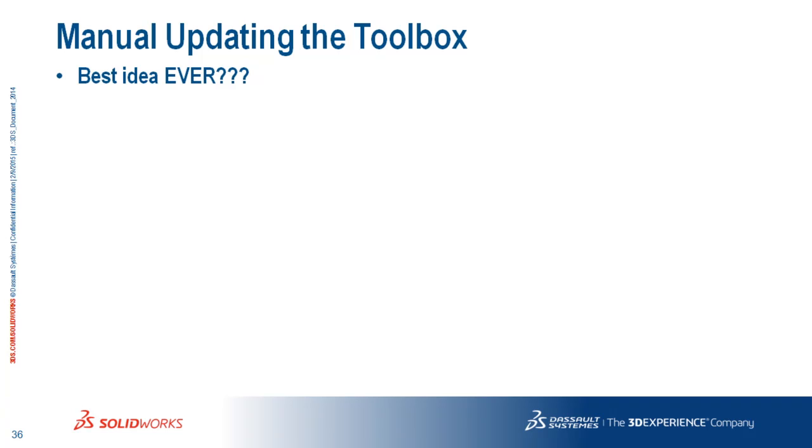Go back in, check it out, yep. All right, so one trick on the admin image to get that to flow through is to just change the setting to write a toolbox to the C folder, C, SOLIDWORKS data, and just dump one on the individual user, okay? What happens then is it just writes one locally and it doesn't have to worry about permissions anywhere else because there shouldn't be anybody in it.